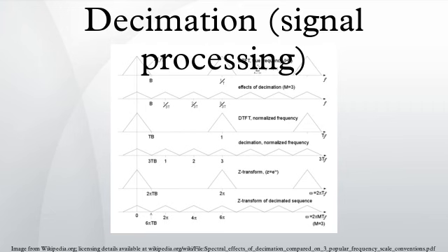Downsampling alone causes high-frequency signal components to be misinterpreted by subsequent users of the data, which is a form of distortion called aliasing. The first step, if necessary, is to suppress aliasing to an acceptable level. In this application, the filter is called an anti-aliasing filter, and its design is discussed below. Also see undersampling for information about downsampling bandpass functions and signals.